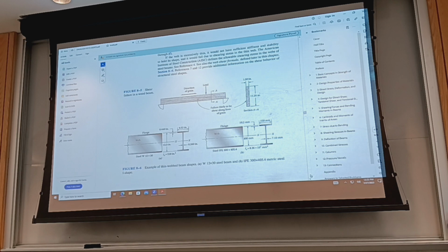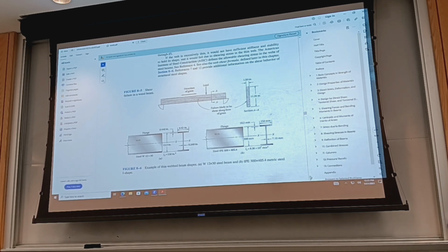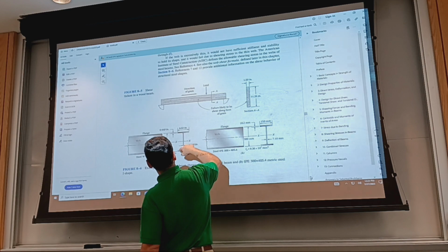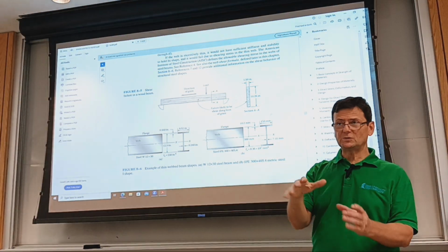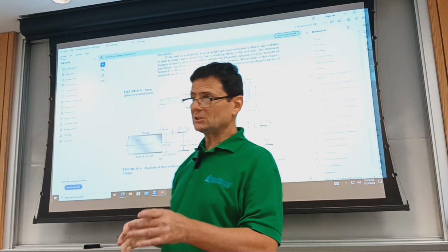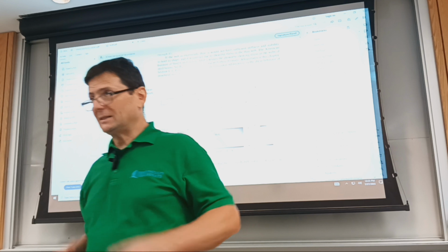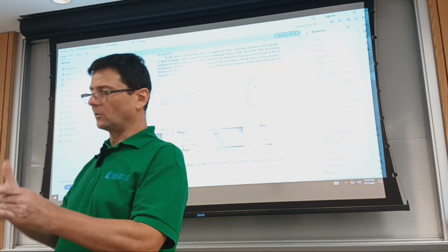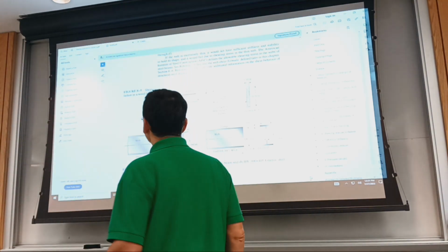And then we have fabricated beams. It could be the case where I'm using a board and assembling two more boards to fabricate an I-beam, or you see T-sections. Have you ever been in an attic in a residential house? I've seen this constantly: a 2x4 and another 2x4 make a T-section, and they are nailed together.